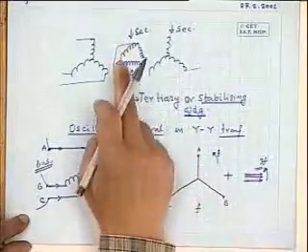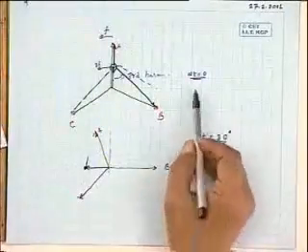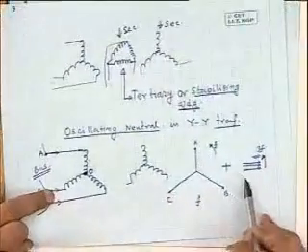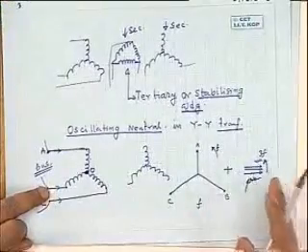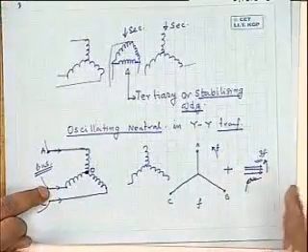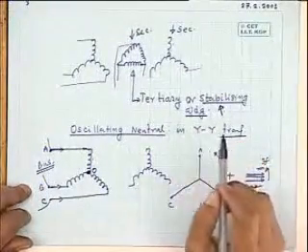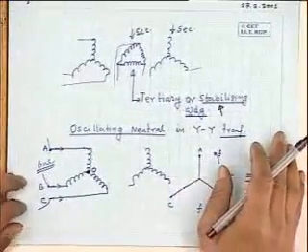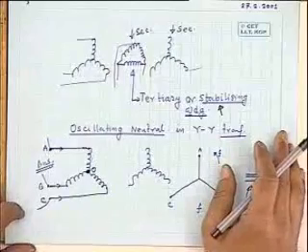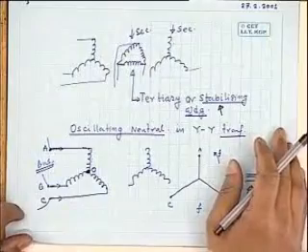This problem too will be solved if you provide a tertiary winding, because the cause of this problem is, of course, these third harmonic voltages which are present. So if you can somehow nullify this, this effect too will not be present. That is why it is sometimes also called a stabilizing winding, which may be present in a transformer, and it will definitely be present in a transformer which you want to connect in star-star fashion.